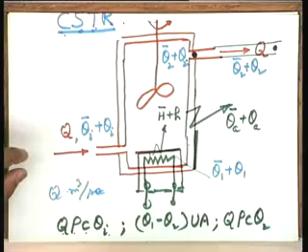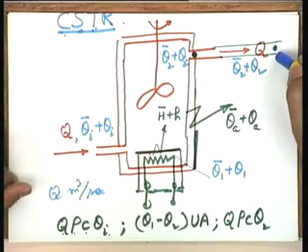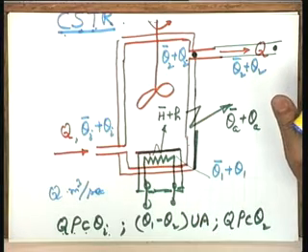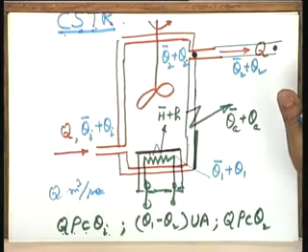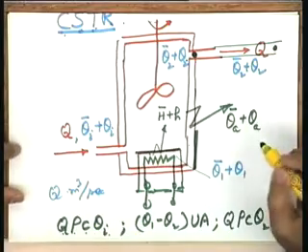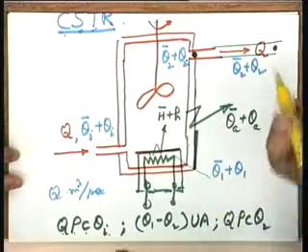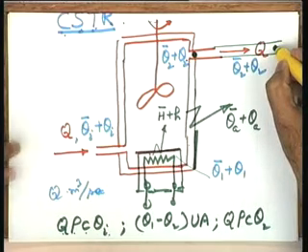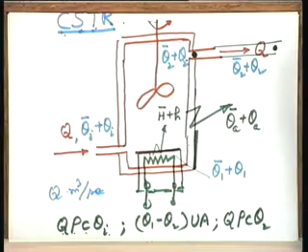industry. Now you will note that if you put a sensor here, your mathematical model which you have derived, the plant model which I have stored in your memory, will change. The reason being, now in this particular case the controlled variable is not theta 2, but the controlled variable is this quantity, because controlled variable is actually that variable which you are sensing.